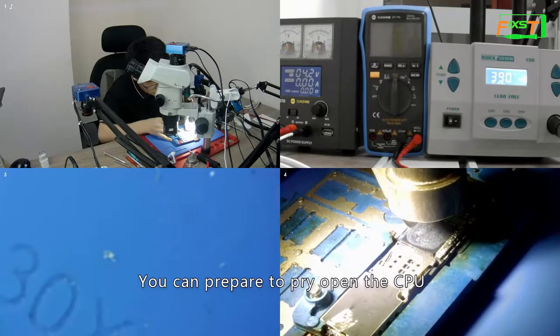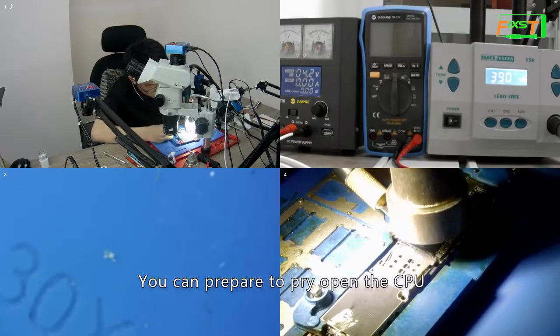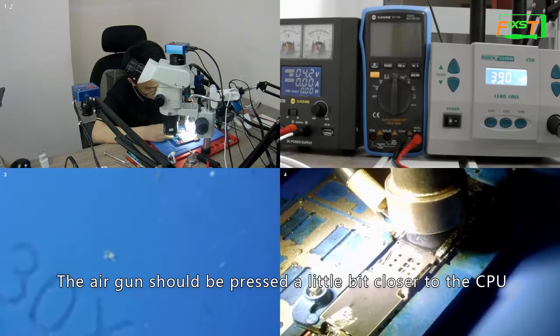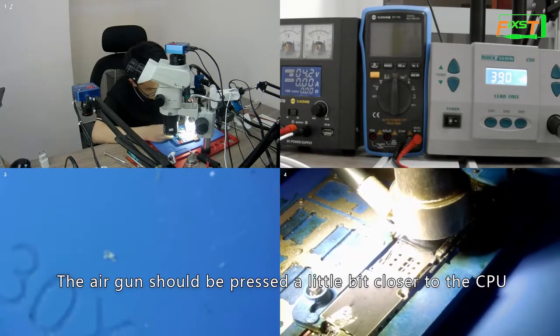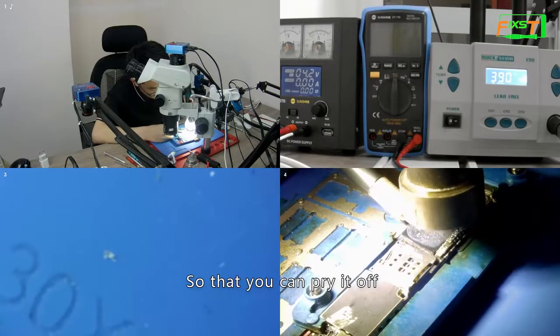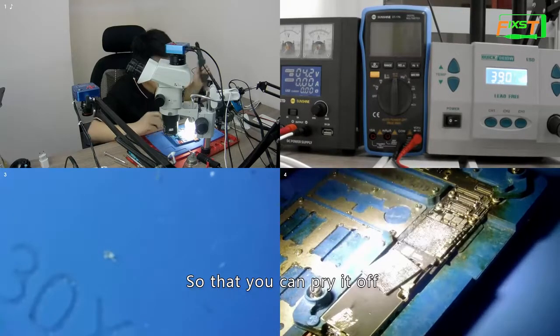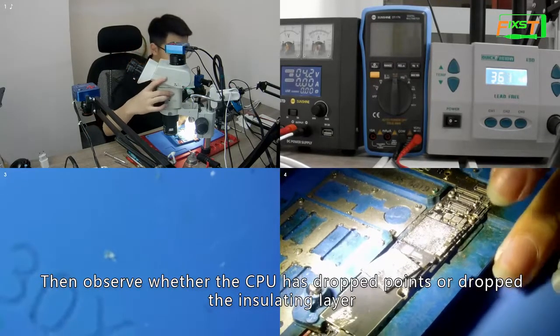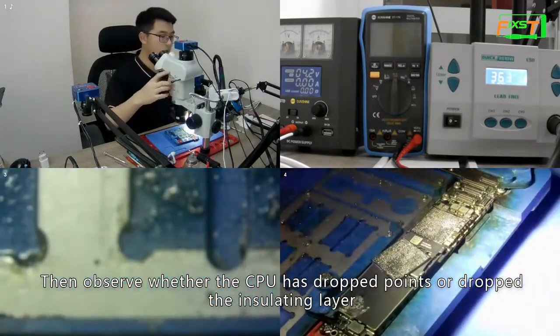You can prepare to pry open the CPU. The air gun should be pressed a little closer to the CPU so that you can pry it off. Then observe whether the CPU has dropped points or a dropped insulating layer.